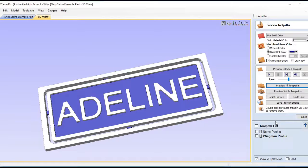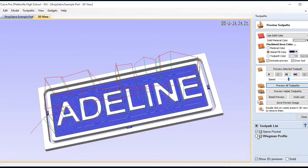Okay, what we can do to save our tool paths, we've got two separate tool paths. Okay, one that is a pocket and the other one is the profile. The profile, remember, is the one that goes around the outside border and actually cuts our sign out of the larger piece of material. Since we are using the same tool for both of these, we can actually save this tool path together, and the machine will run both tool paths one after another.